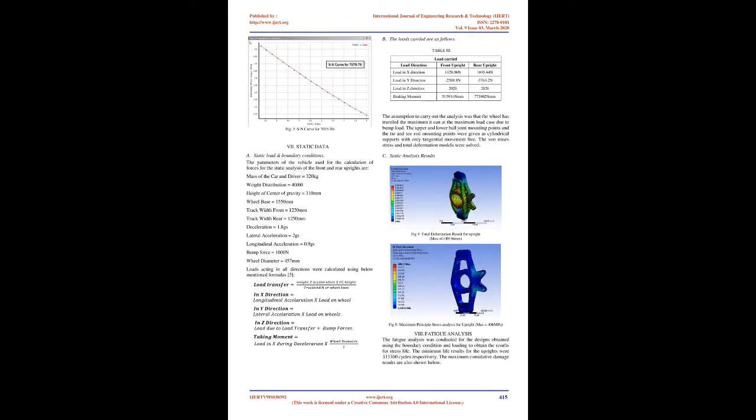It also gives us a formula for calculation of braking force and torque. This formula determines the total braking force of the vehicle, which divides between the brake calipers of the FSAE vehicle. The force of each brake caliper produces a torque about the upright that it is connected to, with the moment arm being the radius of the tire.